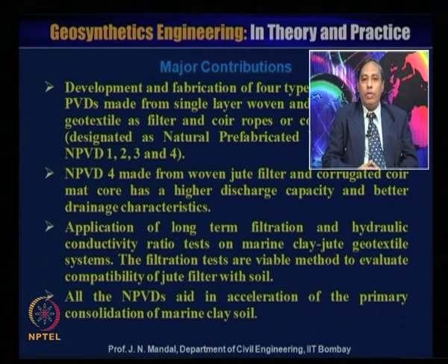Application of long term filtration and hydraulic conductivity ratio tests on the marine clay jute geotextile system. The filtration tests are a viable method to evaluate compatibility of the jute filter with soil. All the natural prefabricated drains aid in acceleration of the primary consolidation of the marine clay.